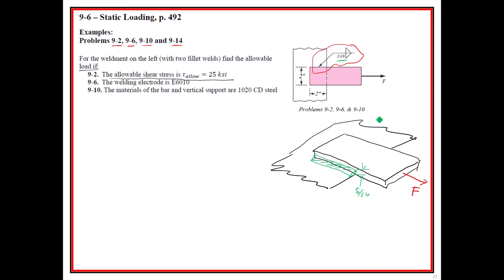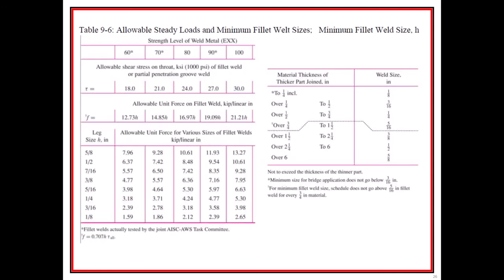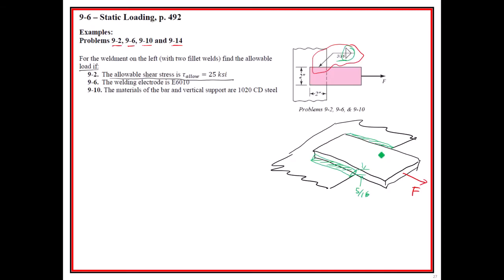Looks like that. And because there's an arrow, this triangle is on both sides, that means that it's going to have a weld also down here. So I'm showing it on the other side. And by that 5/16, we can infer, based on this table right here, from the weld height, that weld size of 5/16, that the plate is somewhere greater than 3/4 and up to 1 1/2 inches thick right here. So maybe it's like 1 inch thick, right?